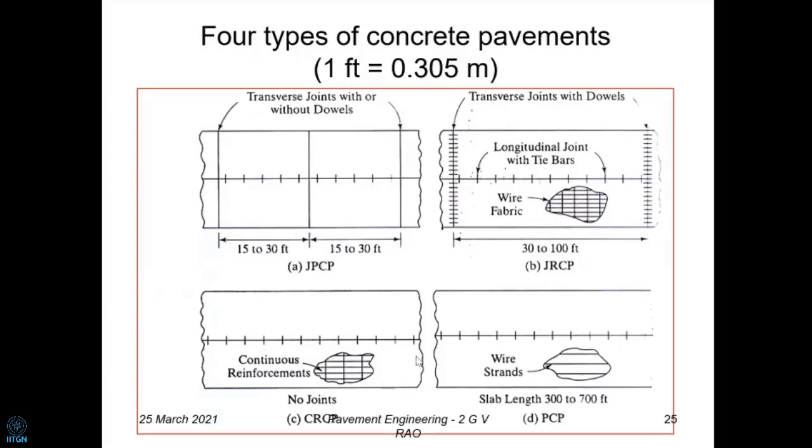Whenever you go over a bridge, between one slab and the other slab, that joint is there. So you jump over the joint every time. So disturbance is caused and you can't go with the speed which is designed. So some people don't like the joints at all. So in those cases, we can have a continuous reinforced slab also. That can be designed without any problem, but it's more complicated than a normal plain slab.